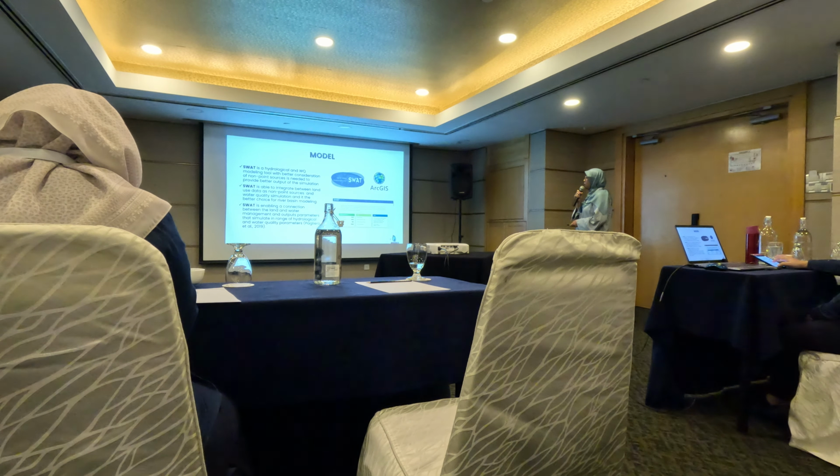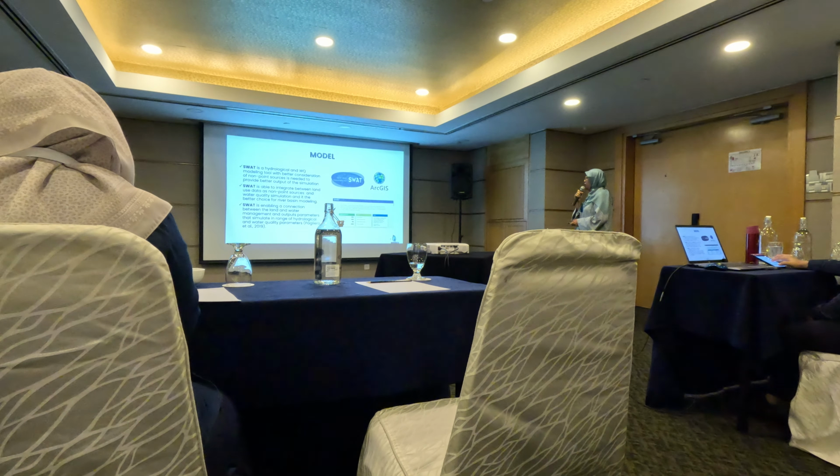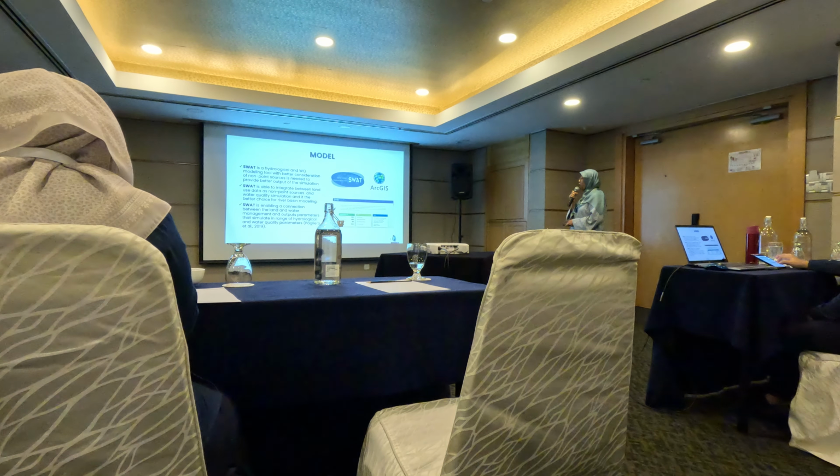There are 3 factors that I considered. SWAT is a hierarchical water quality model, and better consideration of non-point sources is needed to provide better output for simulation. Second, SWAT is able to integrate land use data as non-point source with water simulation, and it is a better choice for river basin modeling. Last, SWAT enables a connection between land and water management and output parameters that simulate a range of hydrological water parameters.